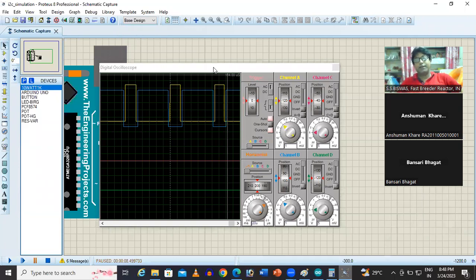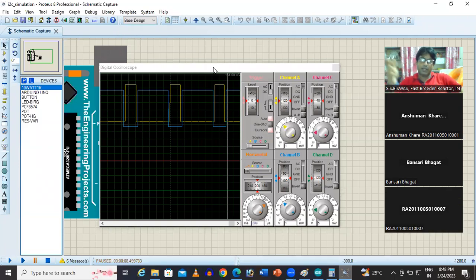Somewhere you need to generate very high frequency PWM. So some friends or maybe some seniors are generating, I think, around... Sridhar sir is developing one induction heating through solar application. So they are, I think, based on the L and C parameters of the coil, you need 25 kilohertz PWM for the occurrence of resonance. So they have made it. I think they have tested.